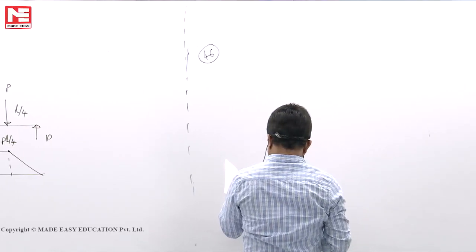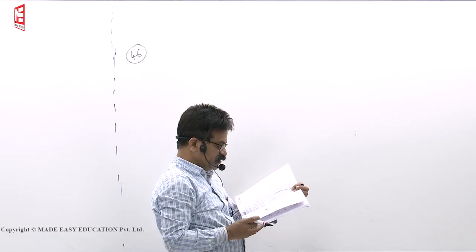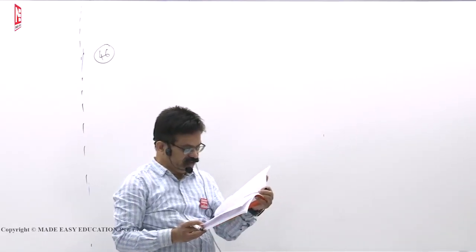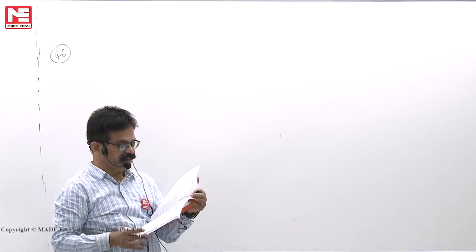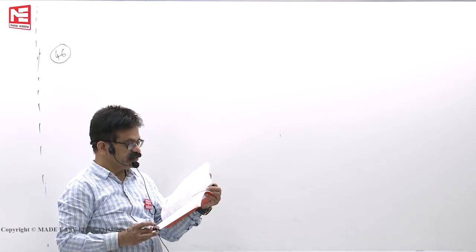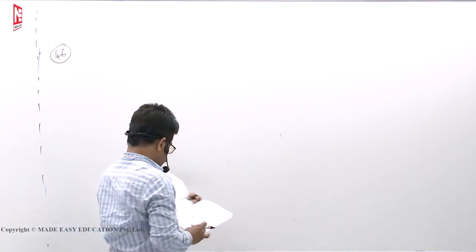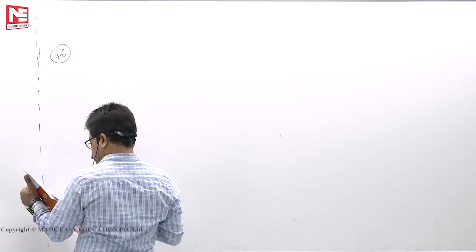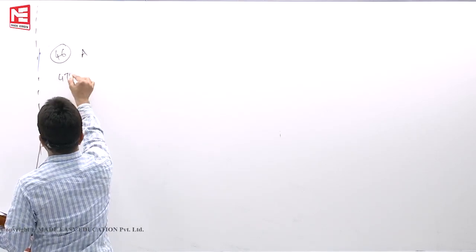A two-hinged arch compared to a simply supported beam of identical span and vertical loading develops lesser bending moment, correct? So, this is also a repeated one, 46. It is like 44 only. So, assertion and reasoning are correct, and the explanation is also correct.